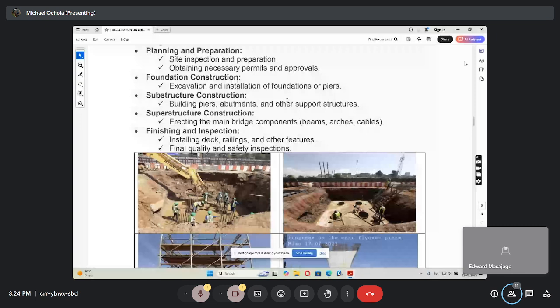This is the tensioning. Post tensioning, you're going to know what it means when you say post tensioning, and when it is pre tension, what does it mean? In post tensioning, you first construct it. After you create the duct, and when concrete has gained 90% of the strength, then you can put in those cables, and then you tension using the ducts here. So this is where the tensioning and locking happens.